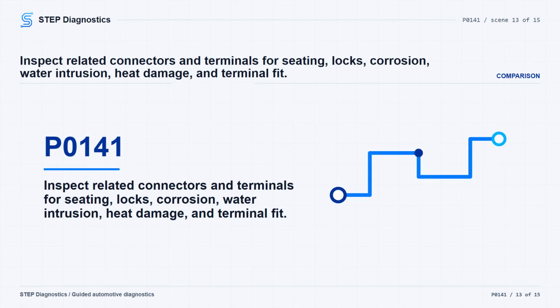With the sensor element, control circuit, and ground circuit checked, inspect the related connections. Disconnect all PCM harness connectors, any related inline harness connectors if equipped, and the related component connectors. Look for connector installation problems, damaged locks, corrosion, signs of water intrusion, seal damage if equipped, bent terminals, overheating from a poor connection, terminals pushed back in the cavity, spread terminals, and poor terminal tension.